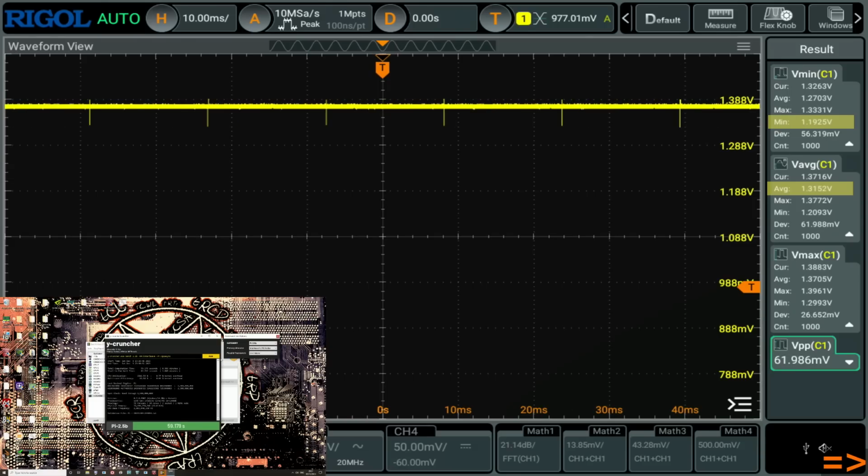So it's a bit CPU specific, and obviously without an oscilloscope, it's going to be very difficult to see if you've set your saturation current too high, or load line saturation too high. But I guess there might be some way to test, and you could probably calculate some basic rule of thumb. Then again, if you're on a 13600K, the CPU pulls so little current to begin with that your idle to load voltage difference is going to be relatively small anyway.